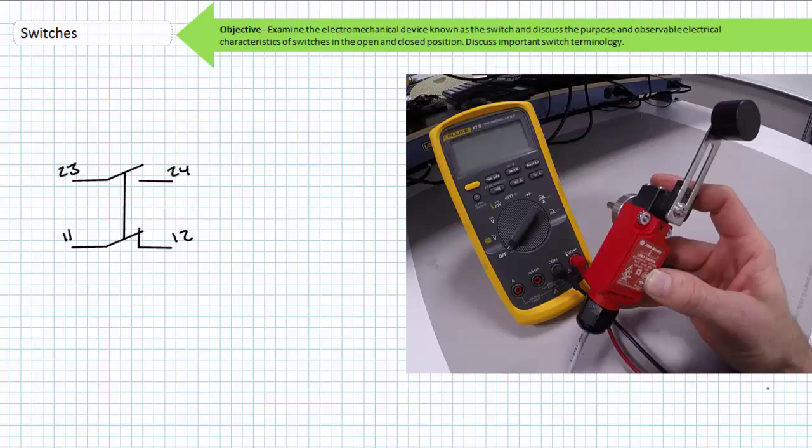For example, modern industrial wind turbines typically feature limit switches inside the blades that indicate a blade has been pitched either to the 0 degree or 90 degree position. As the blade is being rotated into position, a metal tag strikes the limit switch. If the tag is misplaced or the limit switch arm broken off, the controller doesn't think the blade has reached its limit. Ask me how I know this. Actually, don't. This lecture is getting long enough already, and I don't want to make it any longer by including technically relevant and entertaining stories.